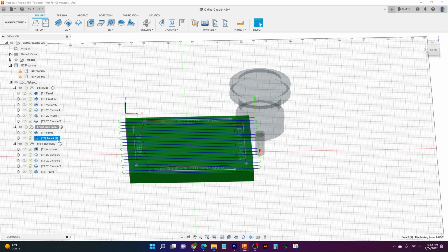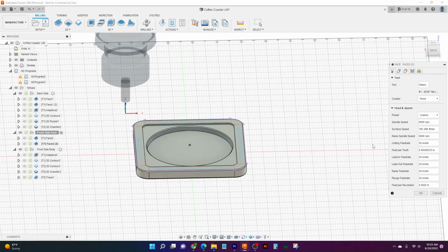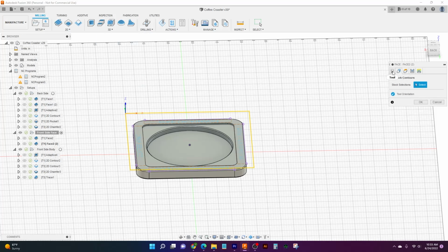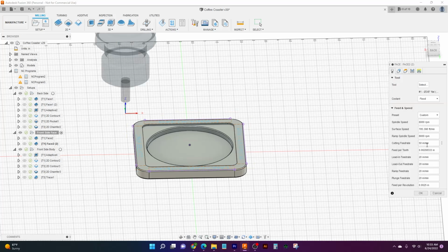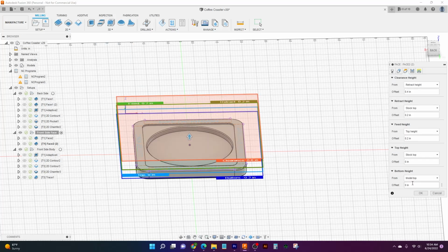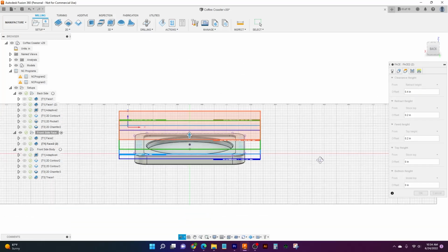And then we have our roughing finish, which is going to be pretty similar, same 8,000 RPM. It's using the same geometry as the previous operation. Cutting feed rate is going to be 50. Lead in, lead out, all of this is going to be 20. I'd say 50 for a finish is pretty good for our facing operation. Gives you that good feed rate. We got a good feed rate on our other half of our part, and so I'm pretty happy with these numbers.